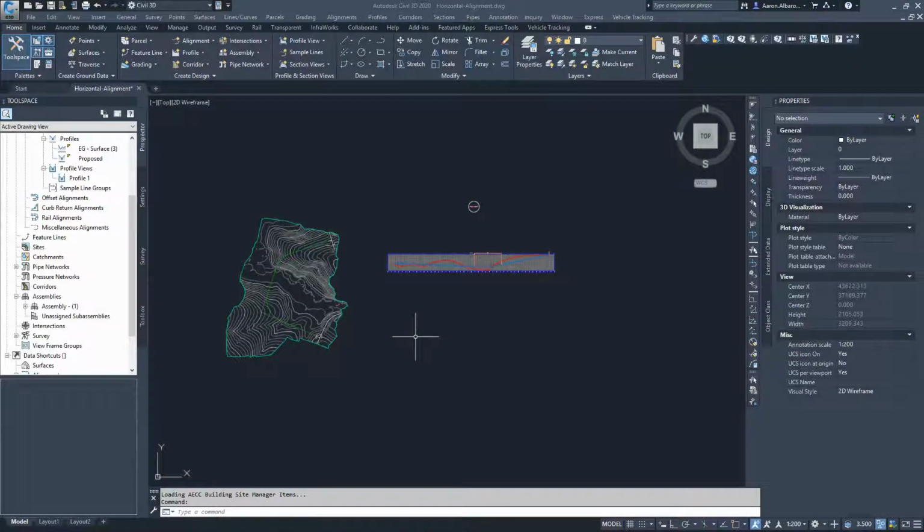Hi everyone, in this video I will start creating our road corridor. This is the first assembly of a few different components that will show us our road in 3D. Currently all the work that we have been doing is in 2 dimensions, so we've got the alignment horizontally, the profile vertically for both profiles, existing and proposed profile.